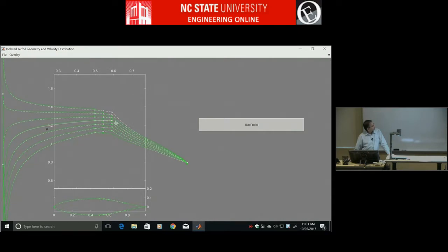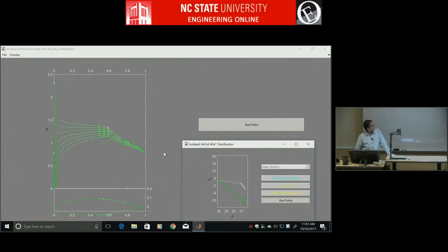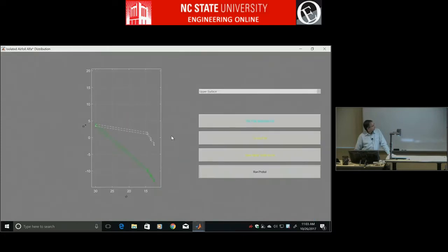So segment number 3 can be more favorable. So I can go to the alpha star window, and no, this one. So this is 1, 2, 3. 3 is too adverse. I can make a cursor edit to say I want it to be somewhere here. So I'm drawing the cursor edit only for segment 3, right? It'll interpolate on the curve that I draw. It'll interpolate any segments that are inside, move those segments, everything else it'll leave untouched.